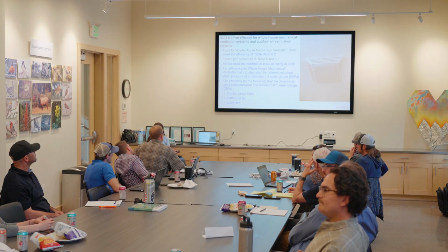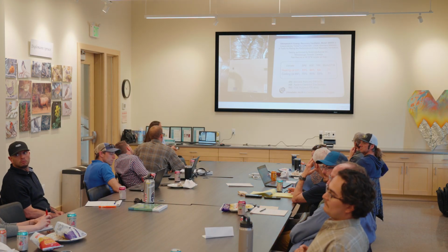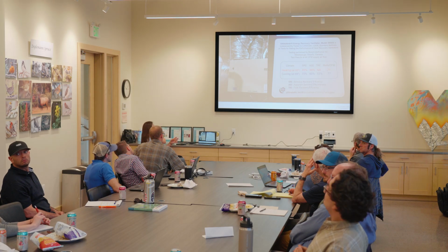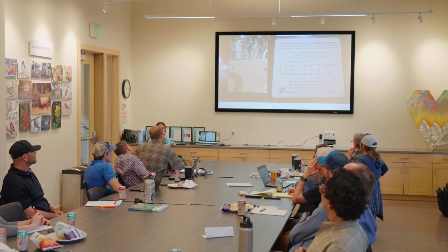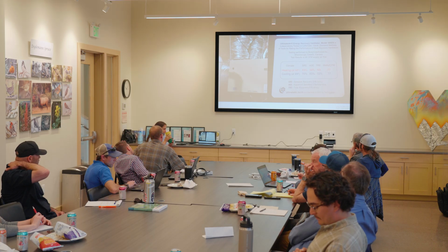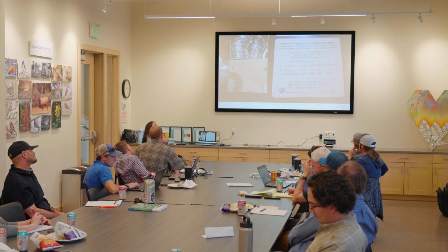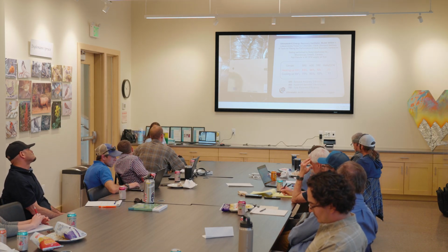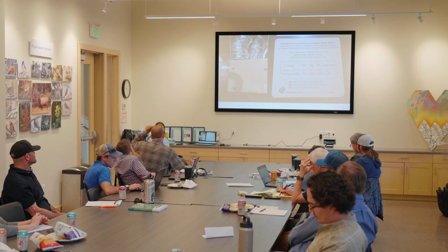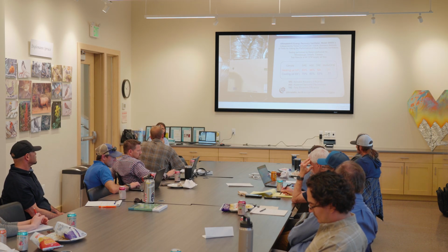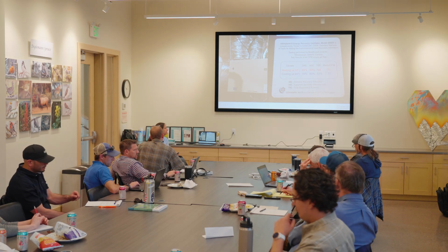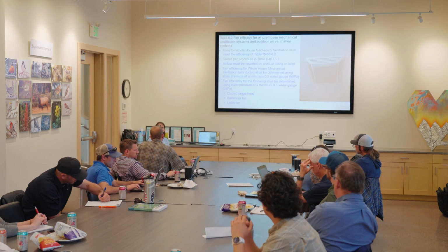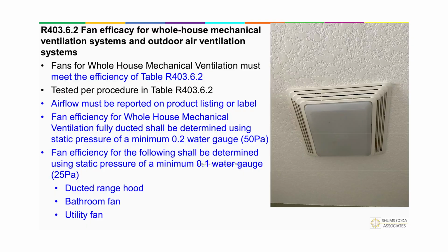By the way, that system has to be installed in a conditioned space. You can't stick it in your attic and hope for the best, as I've seen. It always has to be installed per how the manufacturer requires, and the ones I've seen do talk about being in conditioned space. I see them a lot when they're going in, they put them in closets.